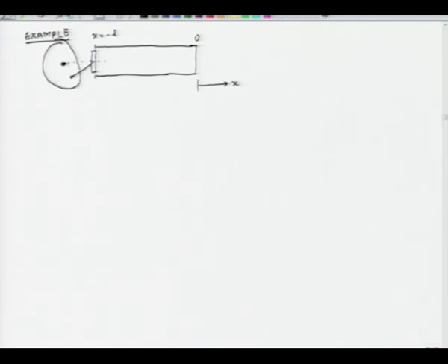So, this circle is rotating like this, and as this circle is rotating, this piston is moving back and forth because of this particular linkage, and let us say it generates a positive pressure wave of P plus, such that at x equals L, the strength of the wave is the magnitude P plus bar times cosine(omega t plus phi).